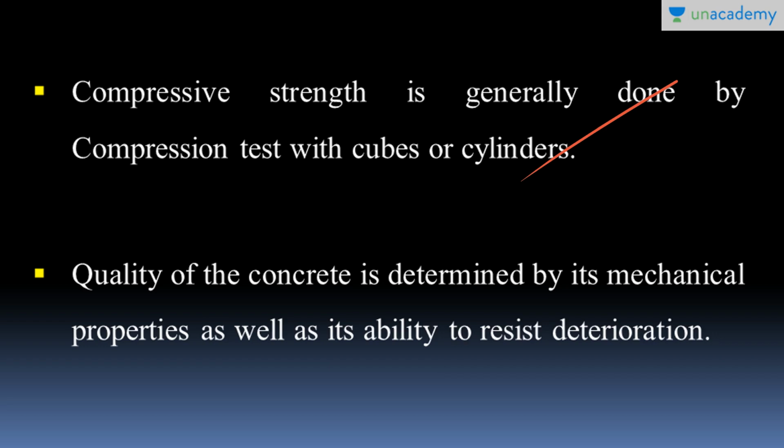It is done mainly in the lab, or it can be done on the field, or by core drilling the hardened concrete on a site. Also, the compressive strength can sometimes be determined by using non-destructive testing. Those were some of the methods to measure the compressive strength.